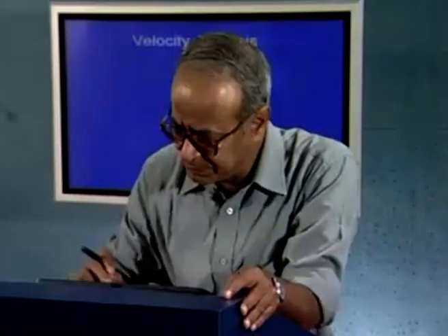In the last module, we have discussed the first step of kinematic analysis under the title displacement analysis. Today, we shall start the second step of kinematic analysis, which we call velocity analysis. By velocity analysis, we mean that for a given mechanism at a particular configuration, if the input velocity characteristic is specified, we should be able to determine the velocity characteristics of all other links of the same mechanism.